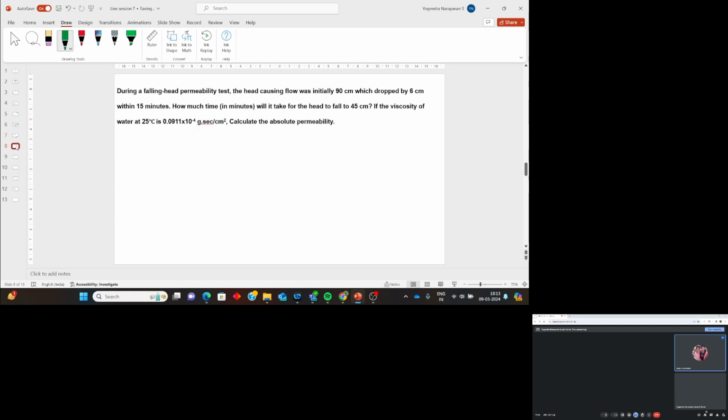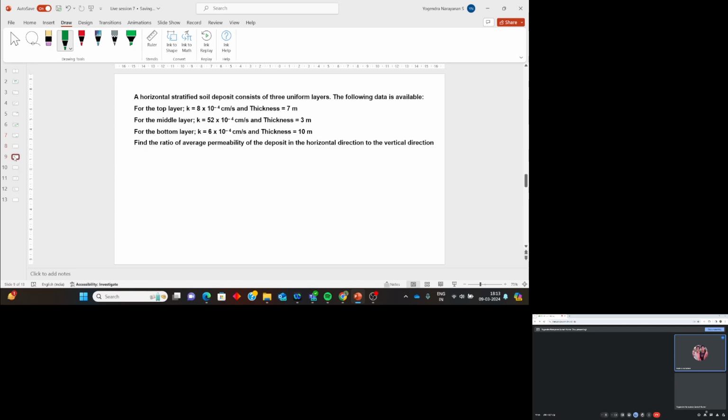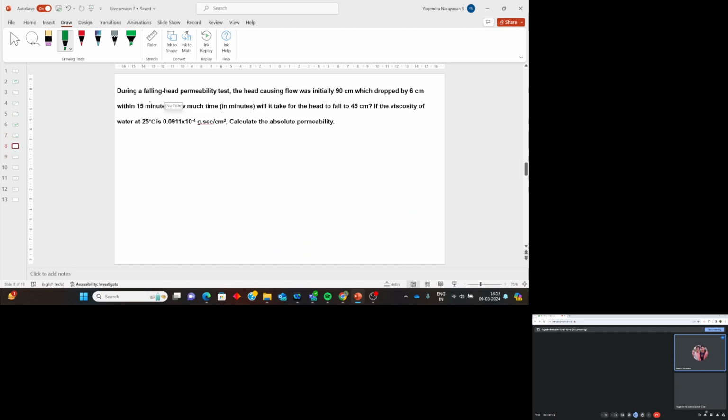Now moving to the next question. During a falling head permeability test, the head causing flow was initially 90 centimeters, which dropped by 6 centimeters within 15 minutes. How much time will it take for the head to fall to 45 centimeters?